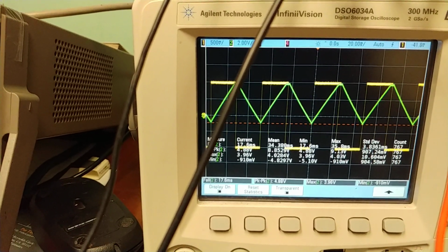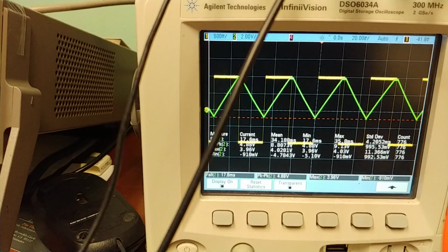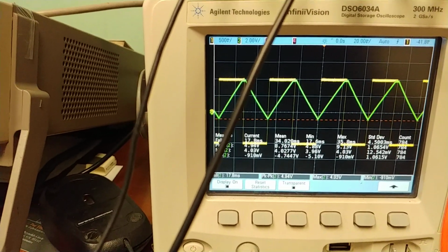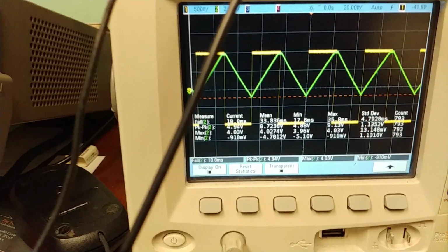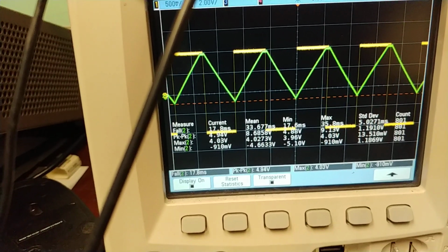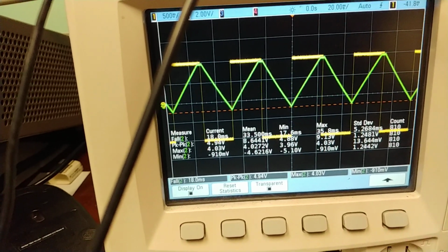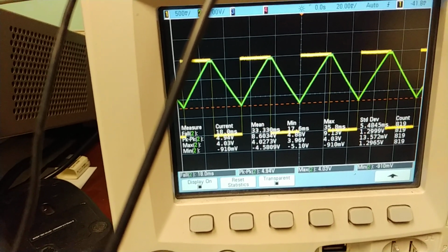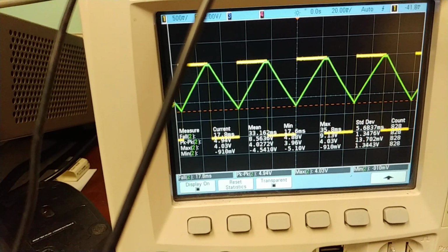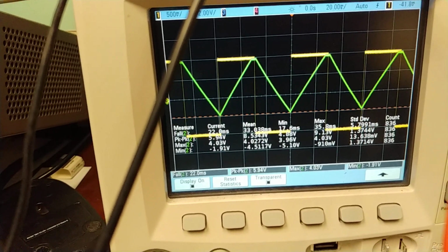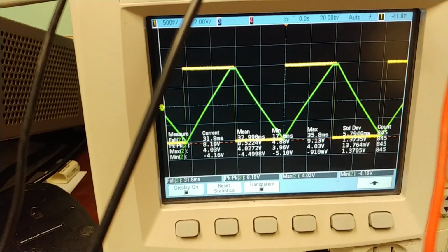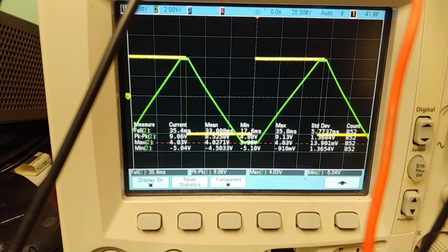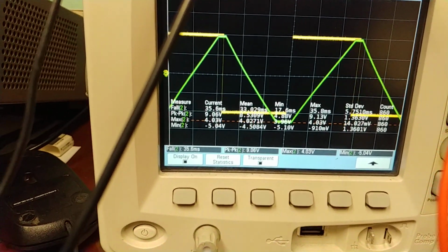It's probably all right. You just go from the high to the low, and still whatever that peak to peak is, now it's like 4.9. Multiply that by 0.8 and divide by the fall time. It should still work, but when it's going rail to rail, you can really see what's going on.